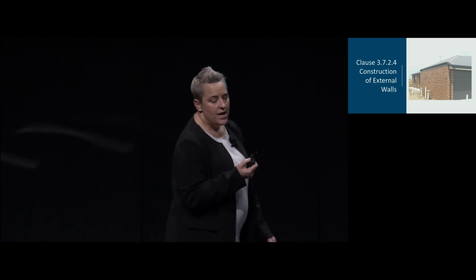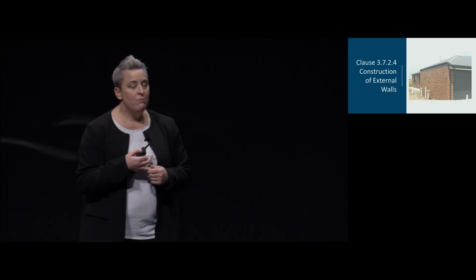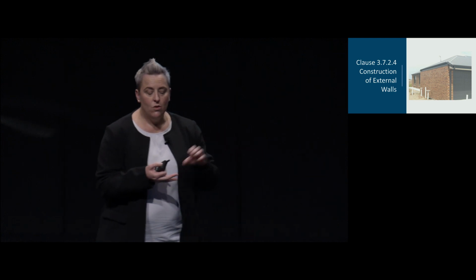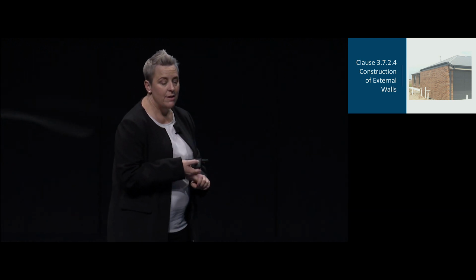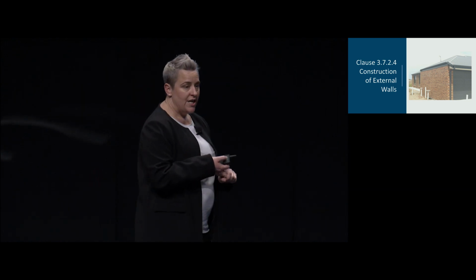So now the code actually has the new provision, and it allows the distance for the termination of the external wall where it may terminate not more than 200 mil from the underside of a non-combustible roof covering. And in order to comply with this, the area must be sealed with a non-combustible fascia, gutter or flashing.